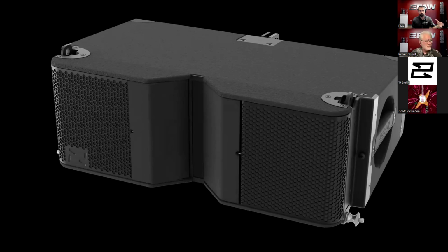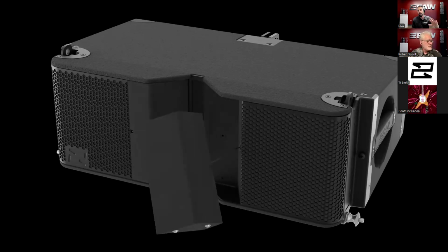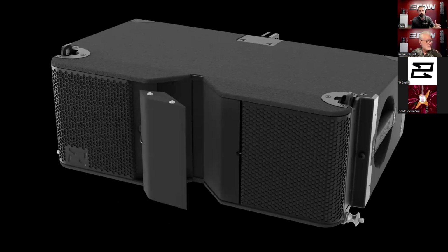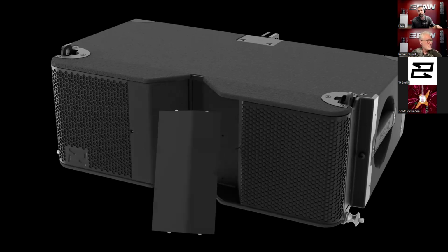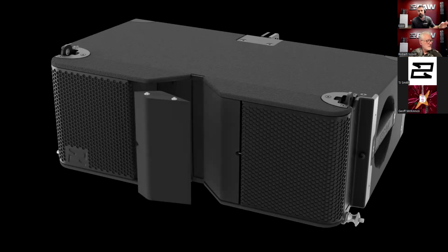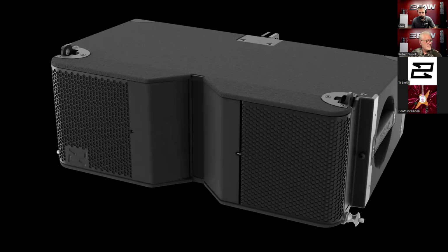And just to reiterate too, this is really flexible. It allows you to adjust for your longer throws when you're using that narrow 80 degrees, provides that even coverage in the near field when you're at 110, or just in general, especially with that asymmetric 95-degree option. It can assist with keeping energy off walls or unwanted surfaces and keep it focused on just the audience areas.